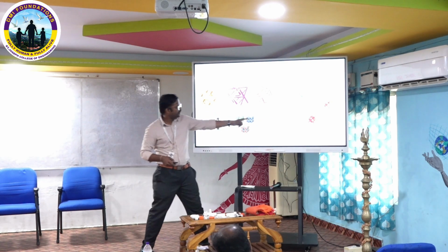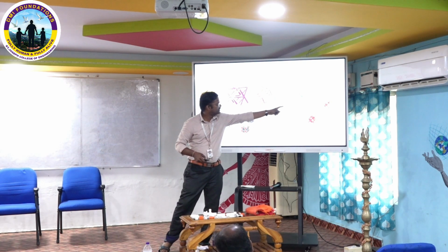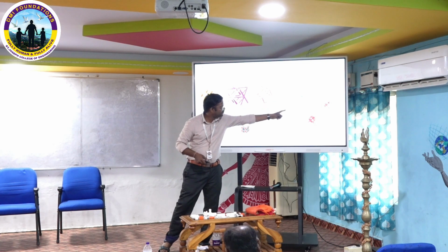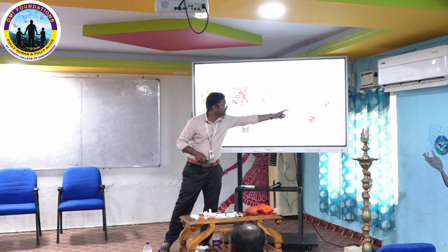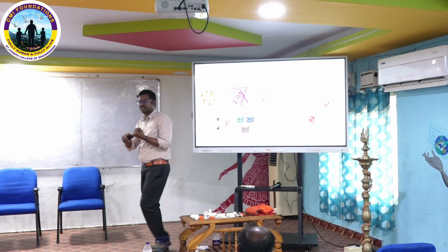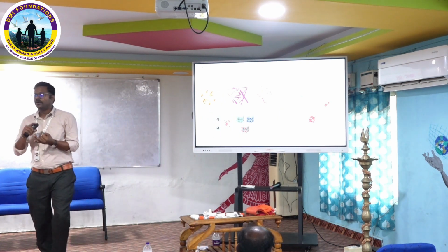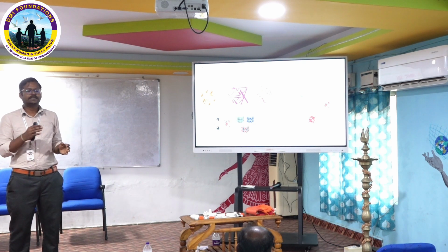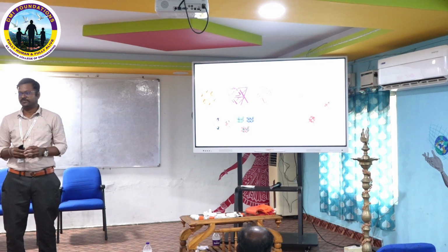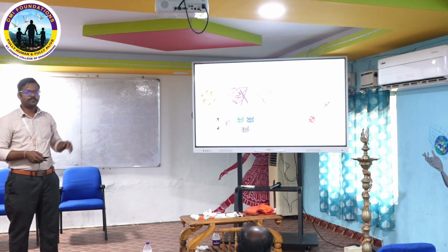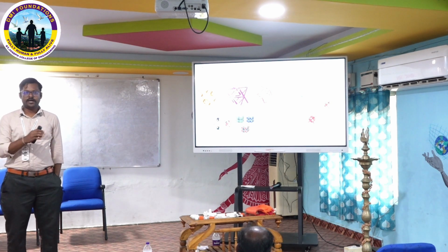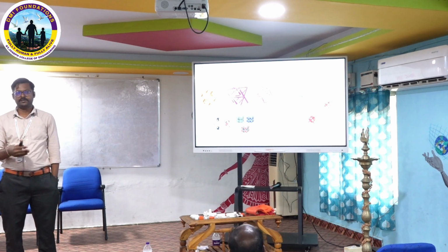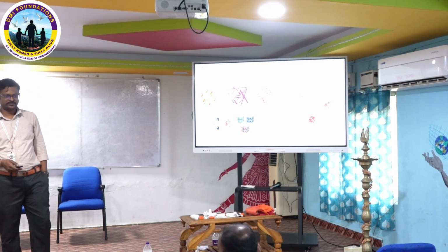The first one is giving more strength. The second one is minimum strength. When we combine both, we can get average stiffness, and also higher energy absorption compared to both other unit cells. So this kind of technology you can also use. This is called interpenetrated lattices. So I stop with this. After taking a break, we will continue.